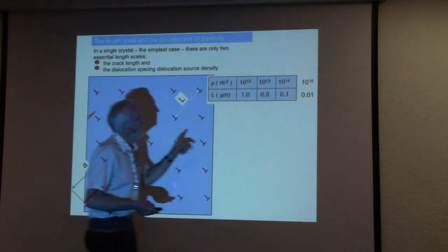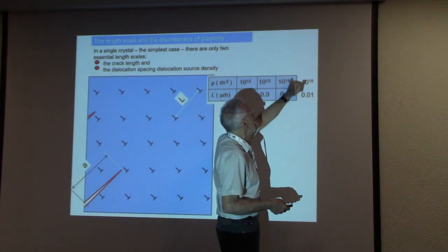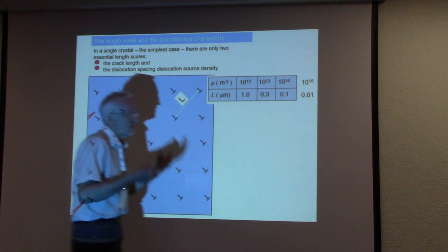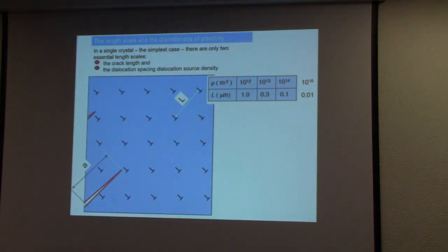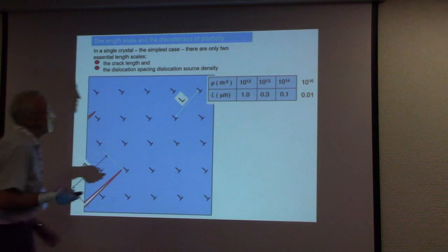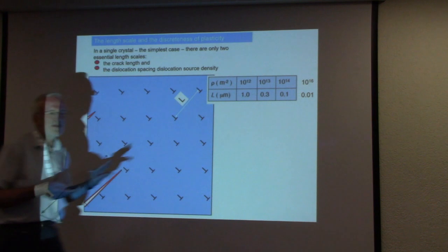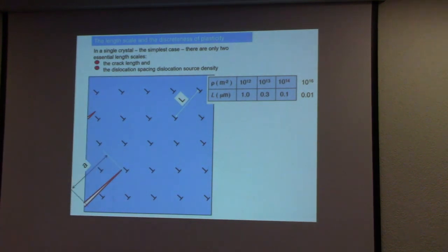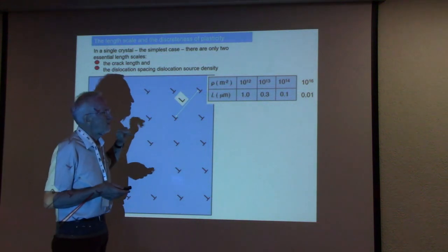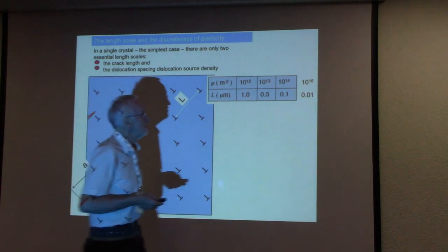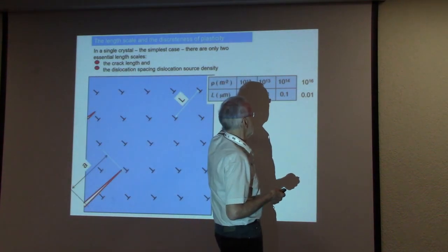When you deform, the standard deformed material has a dislocation density of about 10 to the 14th. So the mean distance is about 1/10 of a micron, or 100 nanometers. If you look with atomistic dimensions, it is not so easy to find them. There are other techniques, the contrast technique in transmission electron microscopy, where you can see it much easier.